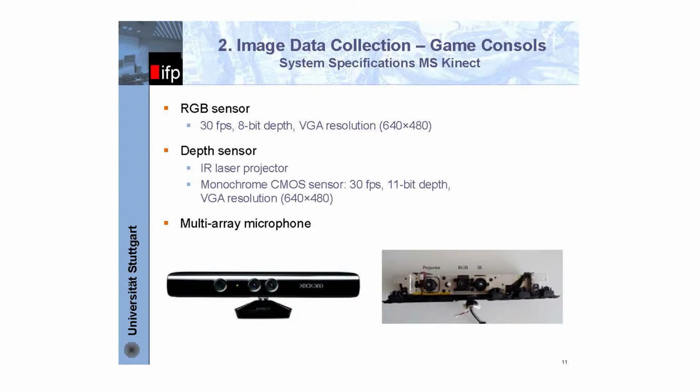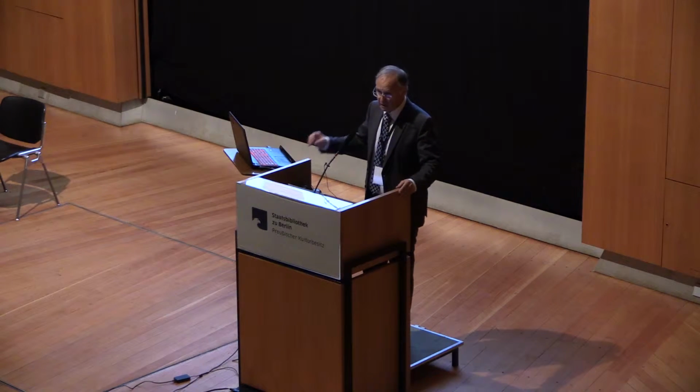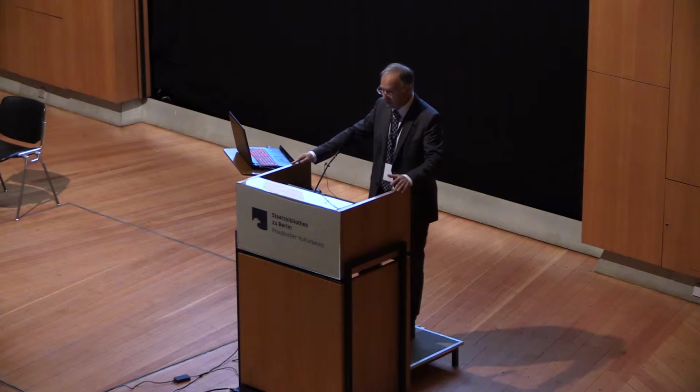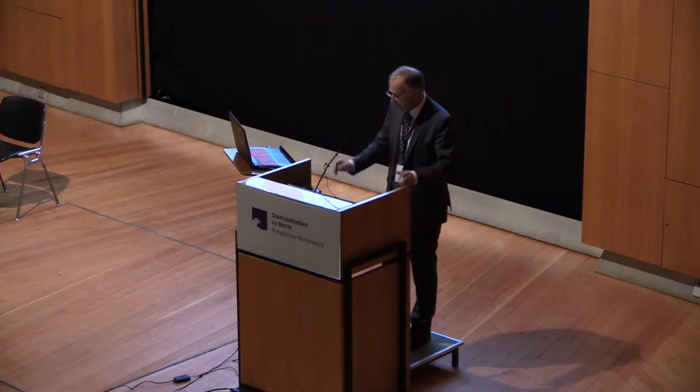You see here the Microsoft Kinect, which also has an embedded stereo system, consisting of an infrared projector, and next to it, 50 millimeters away, an infrared camera, which collects all the pattern of the infrared projector, and we have also an RGB camera just to texture the point cloud afterwards. So that means also here we made very good experiences using this low-cost device for 3D imaging.